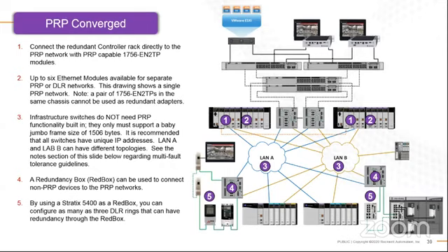All that means is it's able to take non-parallel redundancy devices, tie it into the switch, and then communicate both to LAN A and LAN B at the same time. There's a smart port configuration inside of the switch that says, okay, port 7 and 8 are dedicated to LAN A and LAN B. So similar idea to what we've used ETAPs for in the past for device level ring. Think of this as a big ETAP for parallel redundancy, but it has to be specific to the 5400 style switch.